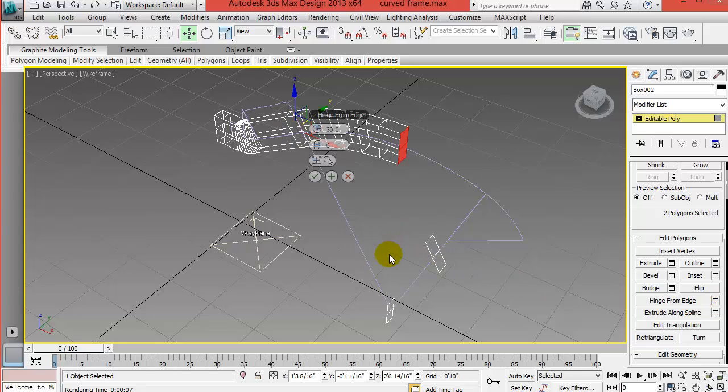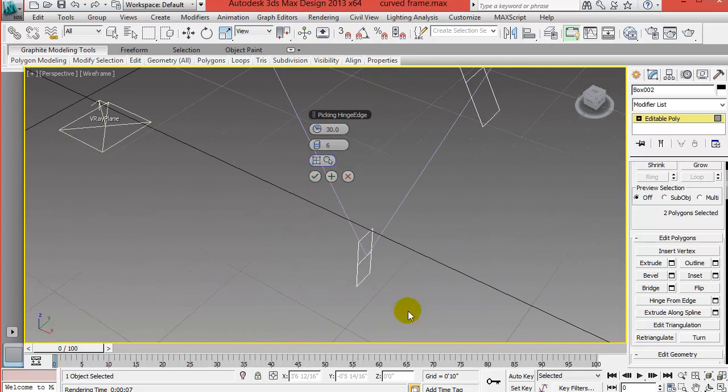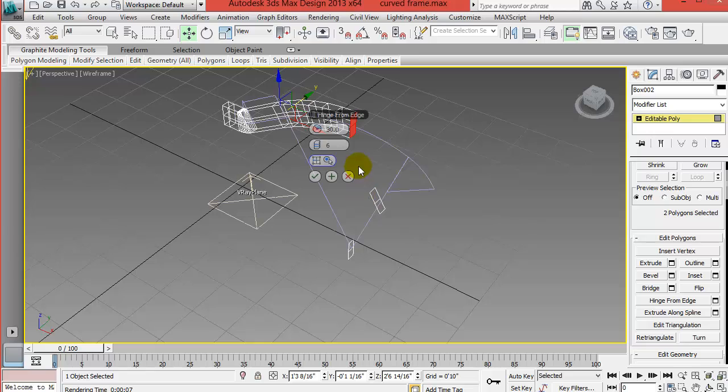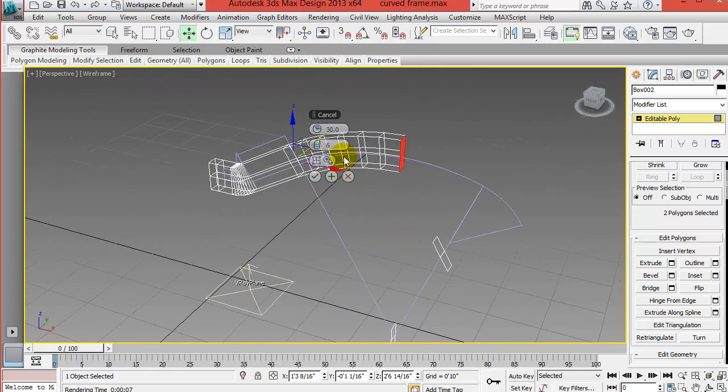So now let's get back to the extrusion so we can finalize. Extrude, selecting the hinge, which is the center line of this here. And then we know the aperture of the pie, or the angle, and you can calculate the value.